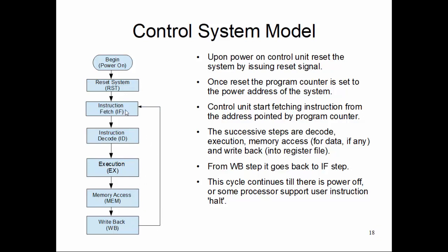It fetches the next instruction, decodes it, involves the ALU to execute that operation, does memory access if needed, writes back the result into the register file and goes for the next instruction. So it goes on in a cycle forever till you shut down your system.